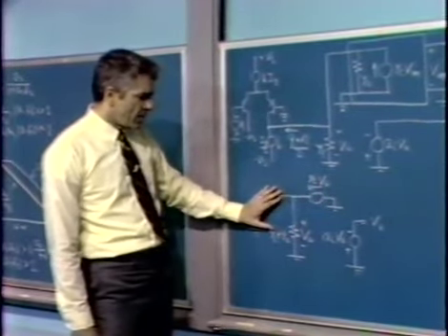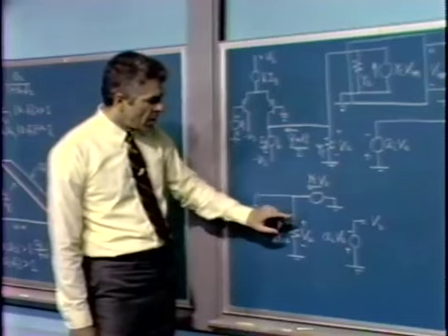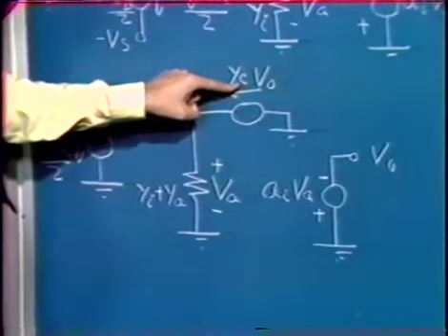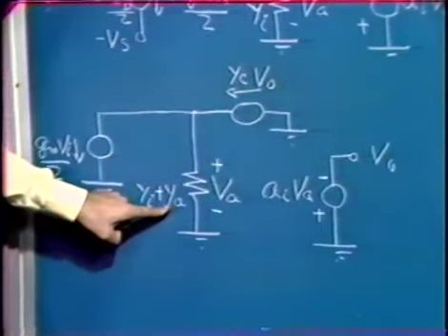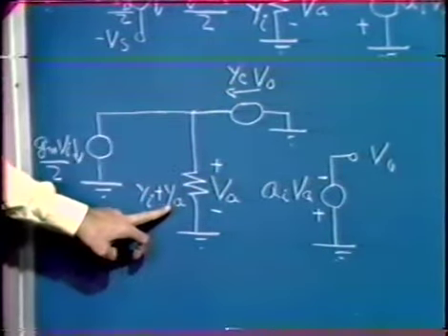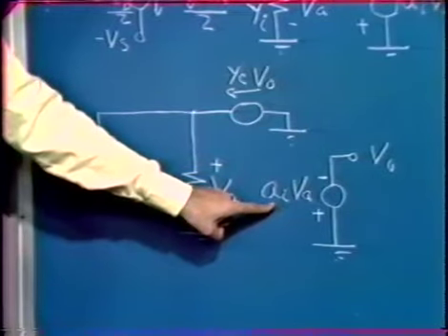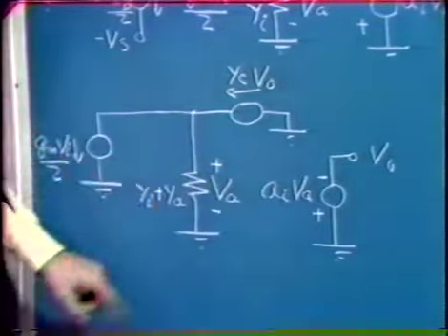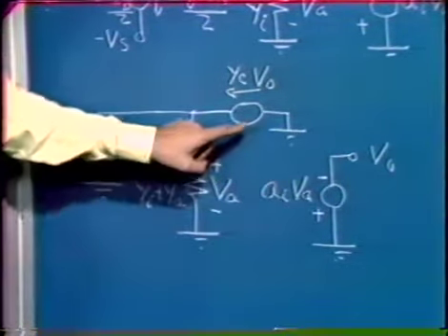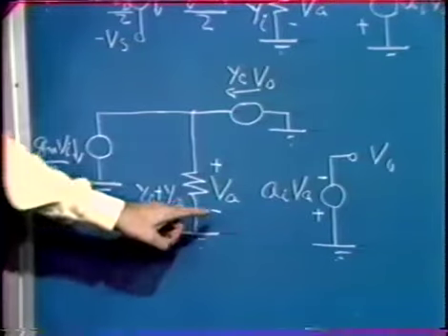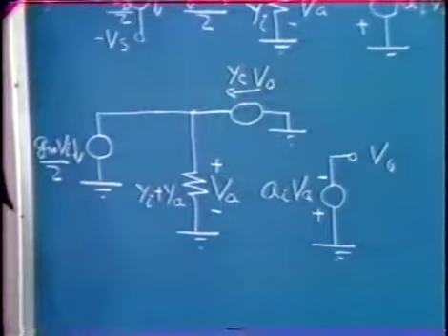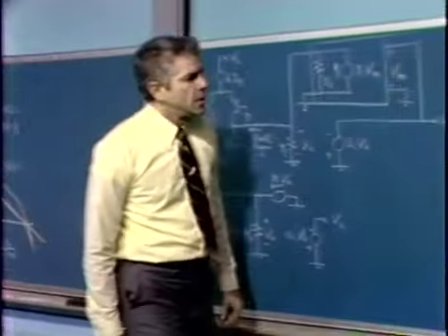If we forget about a driving input to the overall system here, around the minor loop we get a product: Y sub C divided by this admittance to get us a voltage here, so we get a YC over YI plus YA. We multiply that by A sub I, and if we keep track of things, there's a minus sign associated with that loop transmission. So the quantity YC over YI plus YA, all multiplied by AI, is the negative of the transmission around the minor loop.